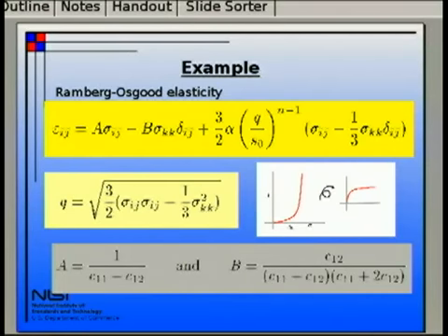And the Q factor is written here. It's essentially the magnitude of the deviatoric part of the stress. So that may be a little bit of word salad for some of you. Stress is a tensor. The deviatoric part is basically the part of the stress that doesn't have any compression in it. So if it's sheared in any direction, this number is large. If you just press on it or pull on it uniformly, hydrostatically, this number is small. And the coefficients there are the ordinary coefficients.